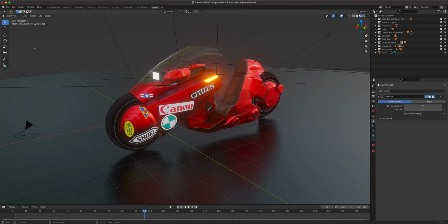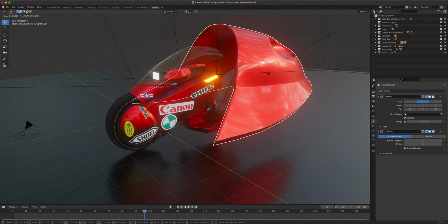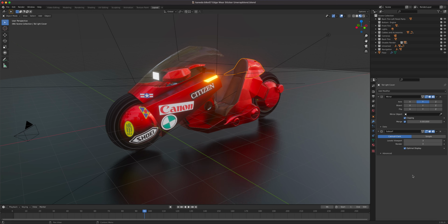Very important in Blender, it's like object-oriented programming. It needs to be in context. So if you're trying to do an operation or activating a tool and it's not working, it's very important where your mouse cursor is positioned. So it needs to hover on the area where you can operate the tool. So let's say I want to resize this object right here, okay? Keyboard shortcut for scaling or resizing is S. So if I press S and then I drag the mouse, I can resize that. However, if I'm parked right here, I press S, it doesn't work.